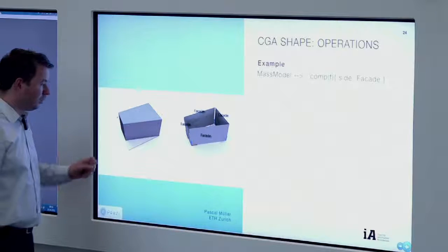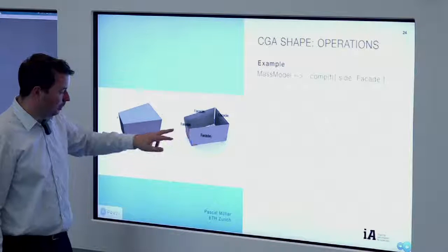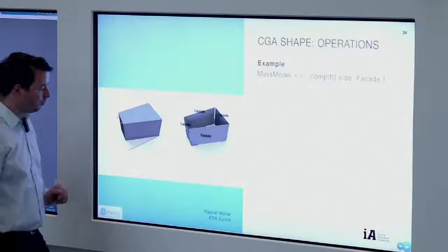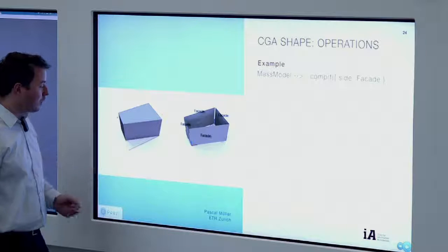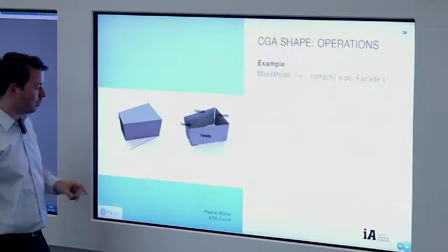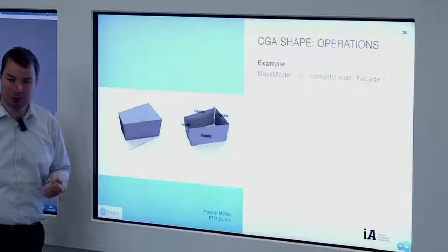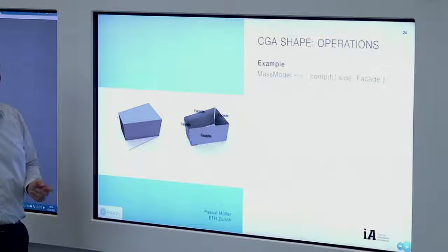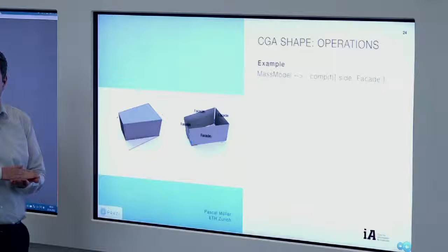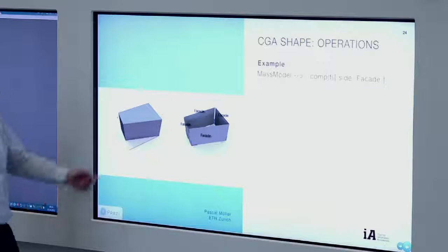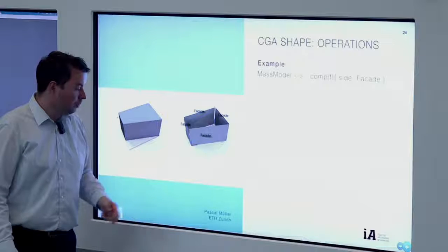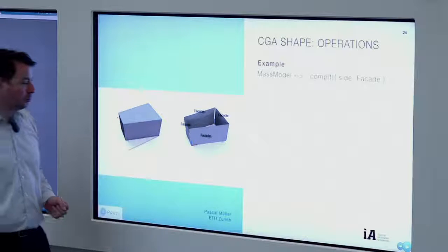But to come to the facade and actually work with the facade, you have those volumes of your buildings or your floors, depending on what you want to do. Sometimes it's good to work with volumes under the floor level, because then you have the proper reporting of each floor area. And then you get the facades with the so-called component split.